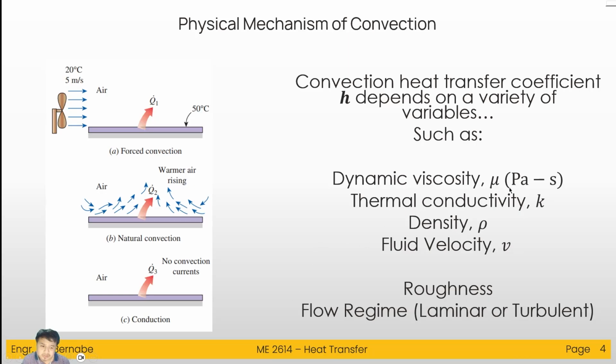So the dynamic viscosity mu, which is in Pascal seconds. In some cases, you might see this as kilogram per meter second. It's basically the same. And then you have thermal conductivity, we already know this, fluid density, and then the fluid velocity.